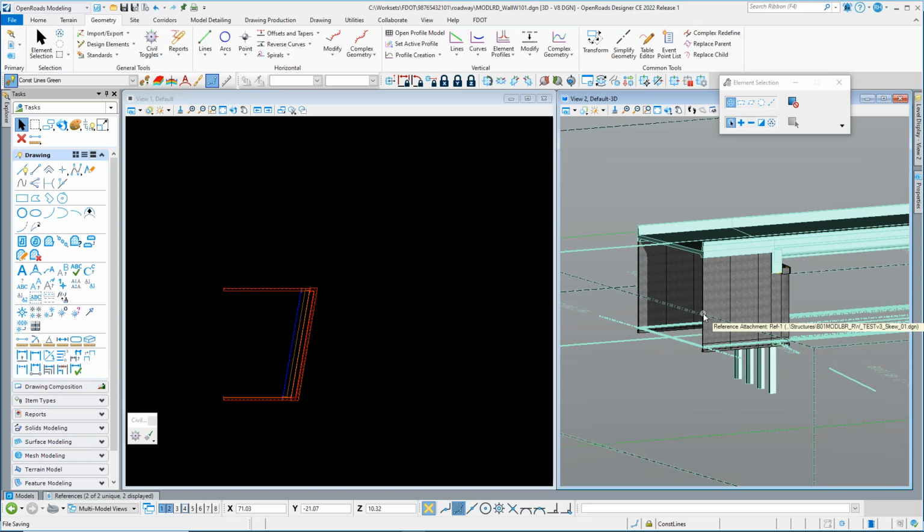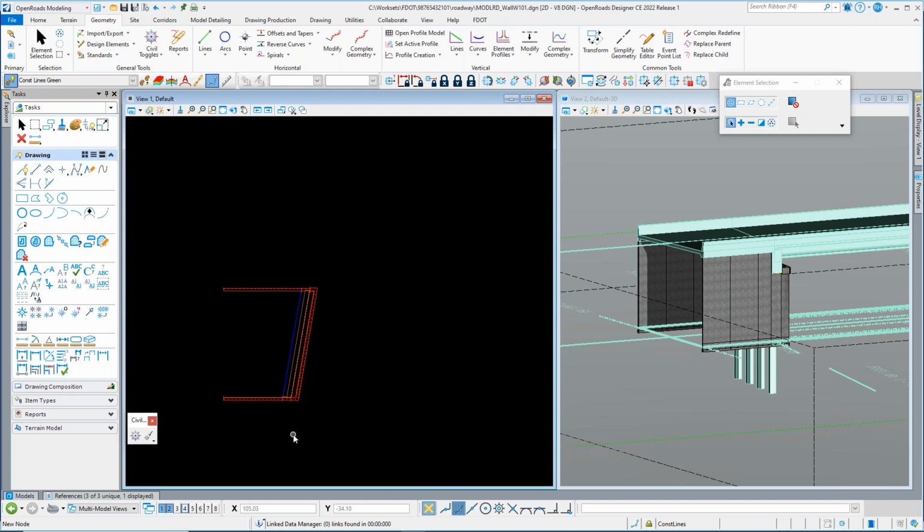The next thing that we're going to get into is we're going to come back into our plan view and actually place some roadway MSE wall at this point. Normally we wouldn't be placing a roadway backbone; we'd place a template in here. We wouldn't be doing that in our wall model file. Looking forward to these wall modeling files being signed and sealed, maybe by the structures engineer, we'd want to keep our roadway separate at this point.